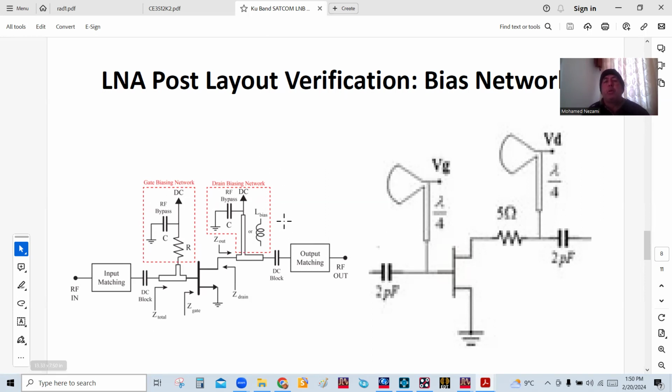Now, at moderate frequencies, we can do this easily with either inductors or a mix of inductors, capacitors, or quarter wave sections. But this point that is short is very critical: we would want this point to be short across the operating band. And unfortunately now, this capacitor, if you look at the impedance of it, it really deteriorates over frequency. So therefore, we can't really get a broadband response where we can present a short to the quarter wave DC bias T. A lot of people call this the bias T line.